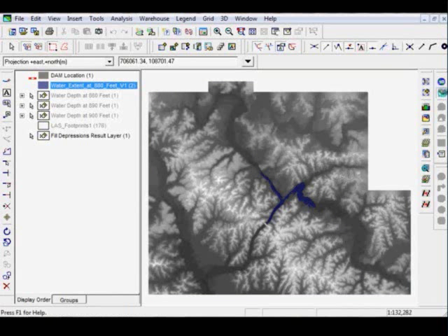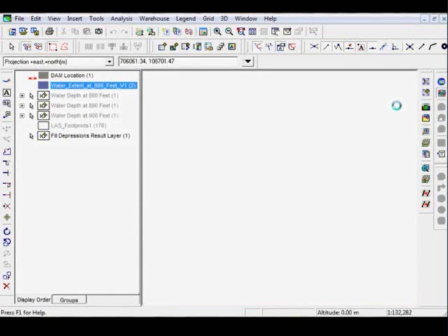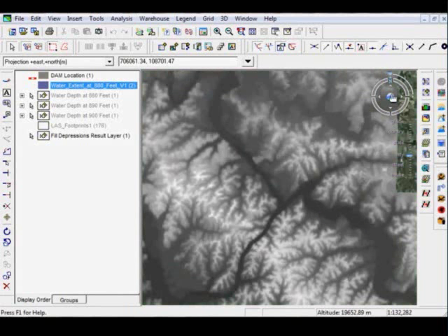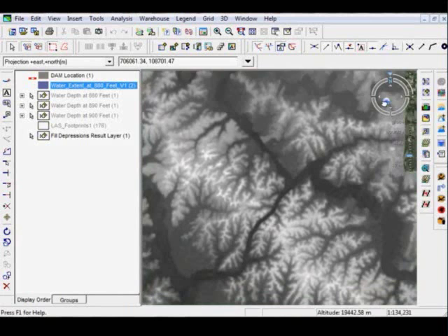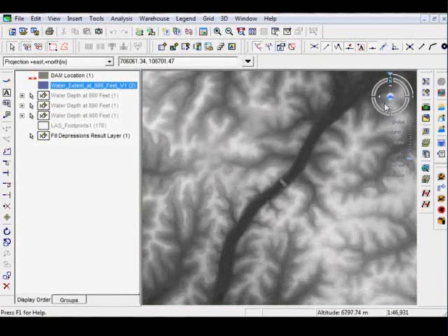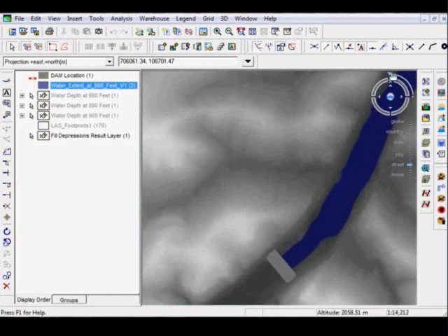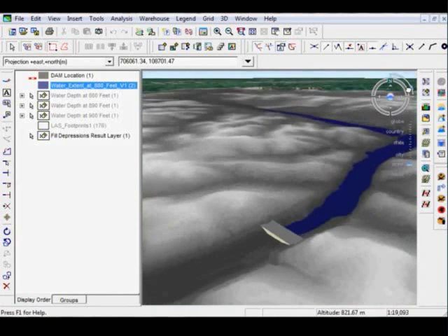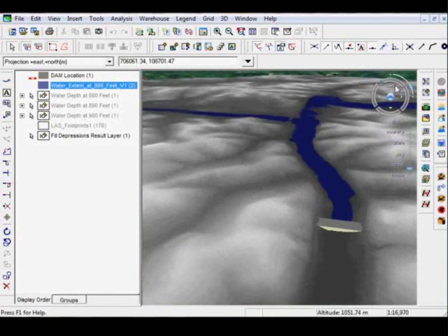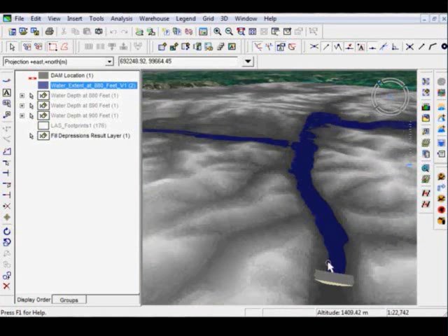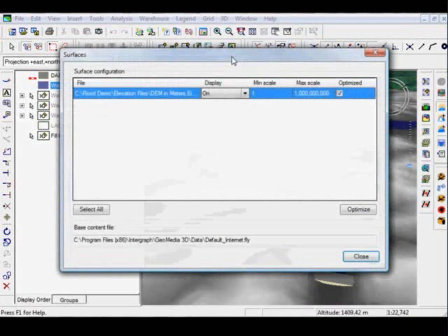So let's pop into 3D and just see what's going on. In this particular case, you'll see that the aerial photographs come in because, again, I'm on the internet, but you'll also see that we have the elevation data coming in. In this particular case, it's just a simple color sequence of a dark gray through to a light gray, and that's been draped on top of that elevation data, okay? But the key component to understand here is that we're using the digital elevation model that we created from the LiDAR workbench as our underlying data source.